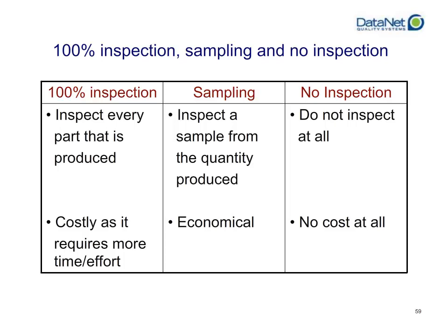Now, sampling is a happy medium between both of these. On the one hand, it's nowhere near as expensive as 100% inspection up front, and it's nowhere near as expensive as no inspection at all down the road. You inspect a representative sample, a rational subgrouping, a rate of your quantity produced, and it actually in some ways gives you better visibility than trying to record everything at all. It weeds out a lot of the natural variation, and it allows you to focus on just the parts that are shifting, assuming that you track this information properly.